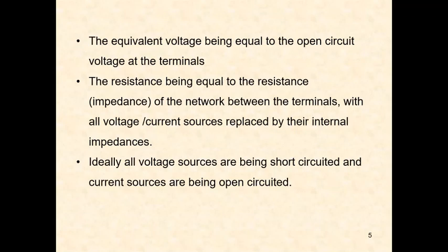So the network is replaced by an equivalent voltage source. How does this equivalent voltage come? The equivalent voltage is equal to the open circuit voltage at the terminals.